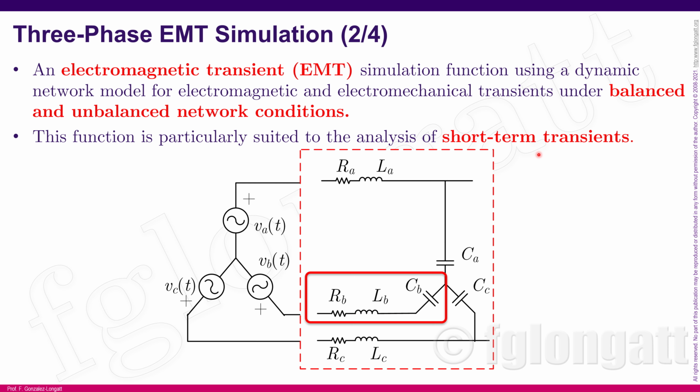I mean, you will need a lot of resources from your computer because the time step is very small, because you have so many differential equations with very, very small time constants, okay? And as I said before, in this kind of simulation, we use the three-phase representation, ABC, and full detail of everything, okay? We need the resistance, inductance, and capacitance of every single component, okay? The reality is this is used for very short time periods, and the time step, as I said, is quite small.